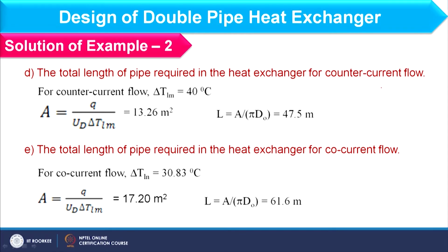So, here if I am considering counter current flow, this is the hot fluid which is moving down because it is reducing its temperature, and the cold fluid moves up because it is gaining heat and its temperature will increase, right. So, considering both temperatures, the hot fluid is moving from 100 to 70 degrees Celsius, and the cold fluid is moving from 30 to 60 degrees Celsius.